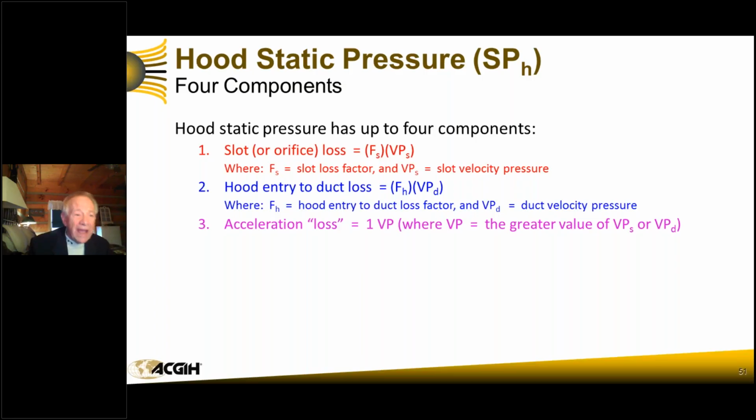What we have to do is take this 0.075 pounds per cubic foot air that's at a dead stop in front of the employee and accelerate it from a dead stop, and it weighs 3/4 of a tenth of a pound. That said, we've got to have enough energy to suck that air in from a dead stop.